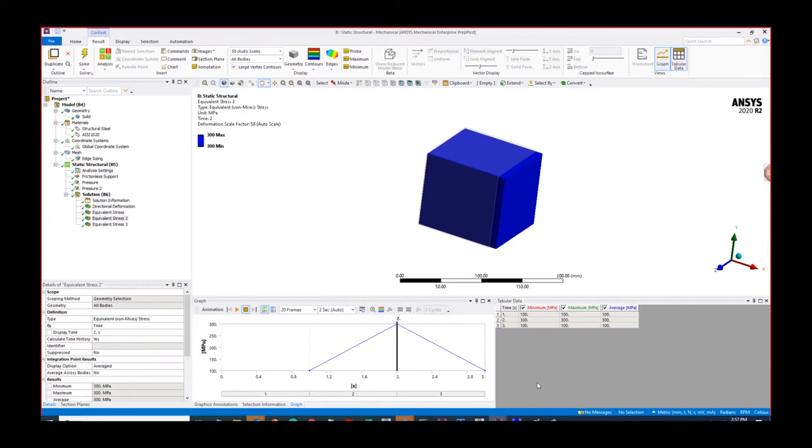The problem is that collecting the SN curve for any material is easy. It is easily available in the literature and there is a large database. But collecting the material input for an EN curve is a complicated process.